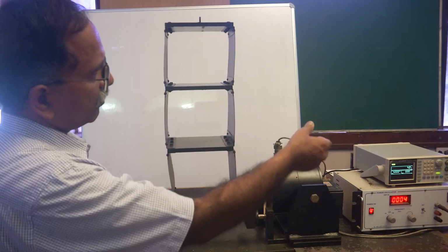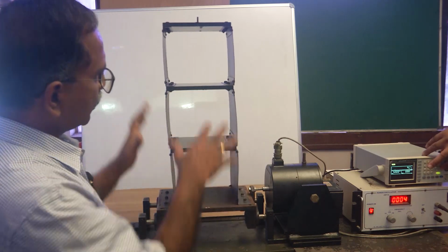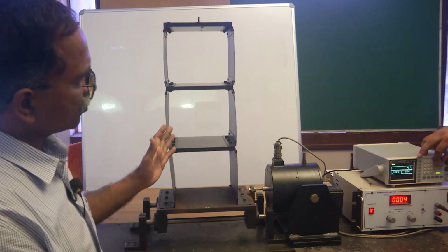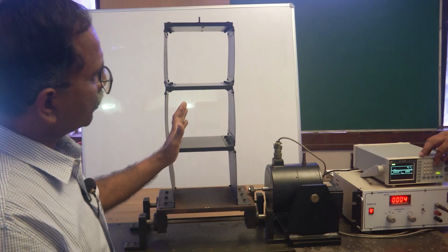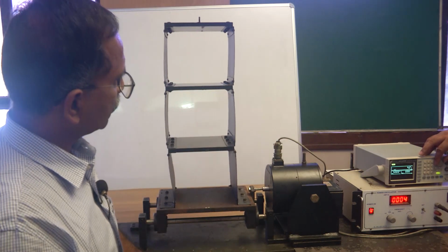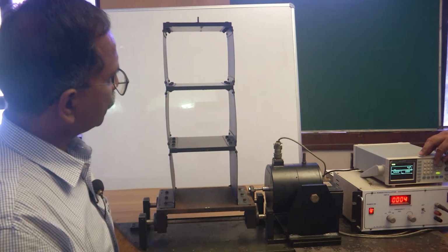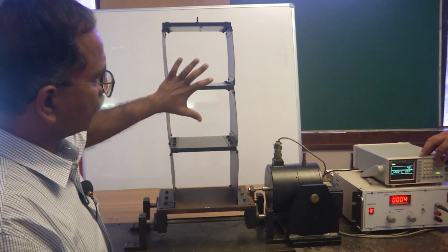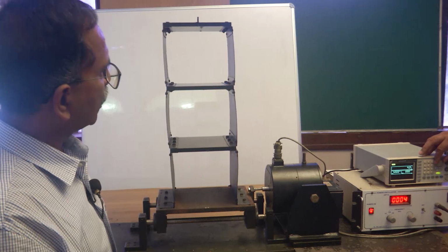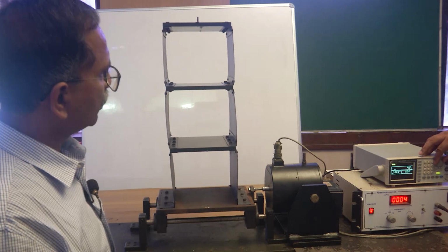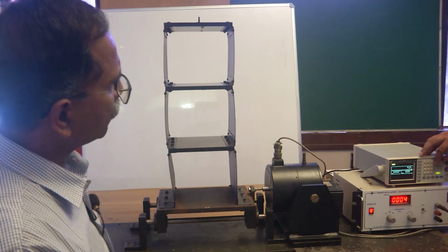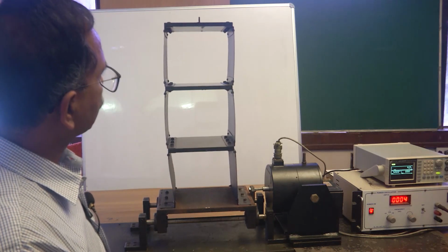Now, we can check that by reducing the frequency whether the amplitude drops, or by increasing the frequency the amplitude drops. Yes, it is quite clear that at 4.1 hertz the amplitudes have significantly reduced. Maybe you can increase it further and see whether the amplitudes reduce. So, obviously, the amplitudes compared to about 4 or 4.1 hertz have significantly dropped. Oh, this is increasing, right? So can you take it to 4.3? Let us check.